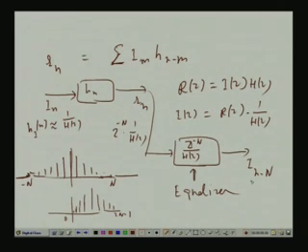Okay. The problem is, if I really know the channel, I know H z, and therefore I can construct this. Unfortunately, the channel is often not known, and even channel characteristics change from time to time. So, we have to do some adaptive filtering, and then it becomes an adaptive equalizer. So, what we do there is the following.